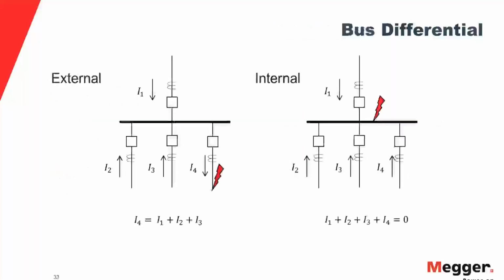The way to overcome that overexcitation condition is similar to what we saw in the magnetizing inrush, which is the presence of odd harmonics, the third and the fifth harmonic. So the same way we implemented the harmonic blocking or harmonic restraint function for the magnetizing inrush condition, we can have the same thing for the overexcitation condition as well.